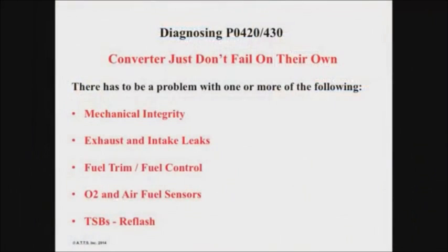So converters just don't fail on their own. They don't just wake up and go, hey, I'm going to die today, and give you a nightmare in your shop, right? There's something that has to kill them. And these are some of the things that are a problem: mechanical integrity, exhaust and intake leaks. And exhaust leaks people overlook. They know about the intake leaks. They forget about exhaust. Fuel trim or fuel control, very, very important.